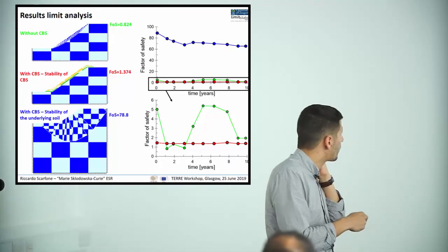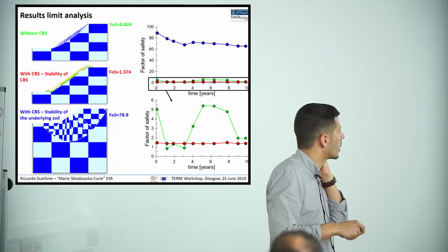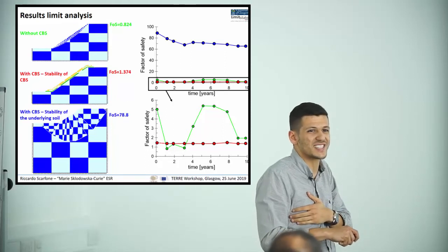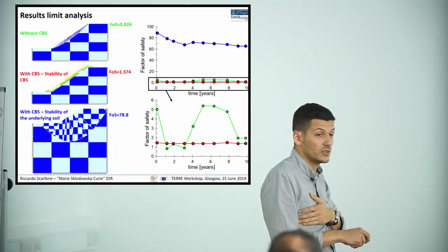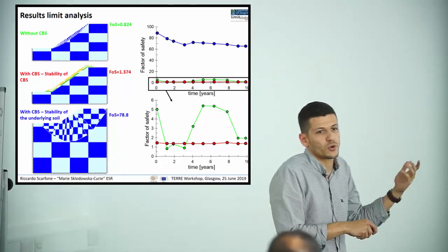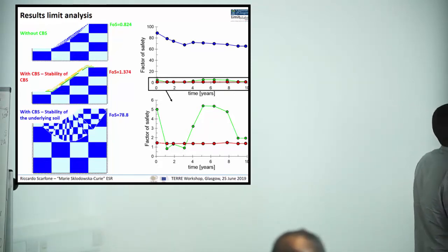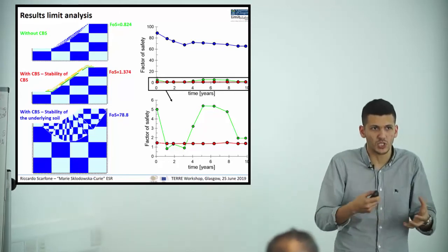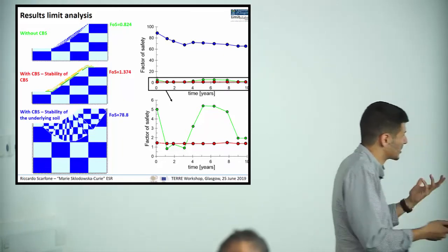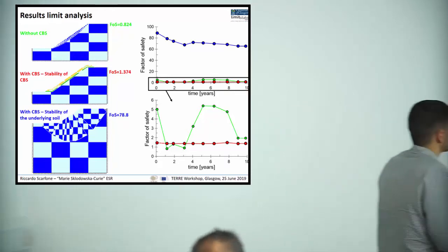Whereas when we place a capillary barrier system, first of all, let's look at the stability of the underlying soil with the effect of the presence of the capillary barrier system. The factor of safety now is extremely higher, around 80. And now the new phenomenon is that we have to focus on the instability of the capillary barrier system itself, but the material which typically forms the barrier has higher friction angles. The factor of safety now is higher than 1, so the barrier is stable now.